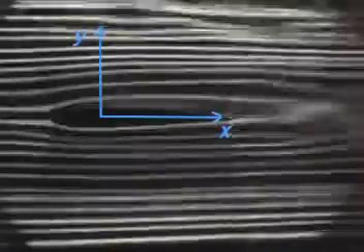In the aerodynamics of birds and airplanes, we can often examine the flow in x and y over the cross-section of a wing and ignore any changes in the direction of the wing span, z. Here is such an example in a wind tunnel where smoke is used to visualize the flow. The length of the airfoil in the flow direction is called its chord length.